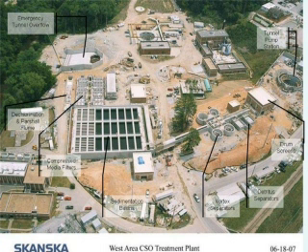The area upstream of the bending weirs is a pretty flat area, and it actually settles out a lot of material. This is purposely done so that the city can scoop up the grit materials before they go into the tunnel. What the city has found from the tunnels they built in the mid-'80s was that after about 20 years, the tunnels were close to half full of grit material. They spent quite a bit of money a few years back scooping that material out. They tried different ways of doing it. This is put in to keep those materials from getting down into the tunnel.